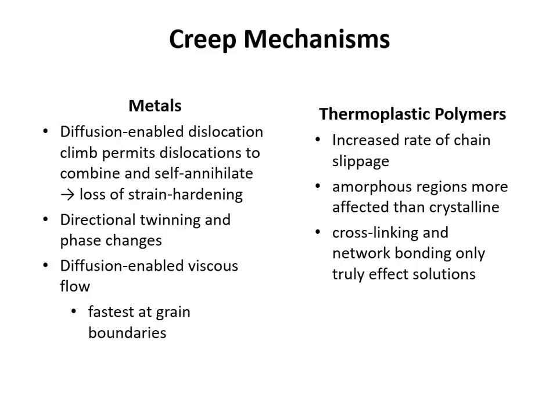You're giving things temperature, so basically the applied stress that a metal is under in service will apply a drive for the material to deform. Generally, this will occur by dislocation movement. You're now giving it enough temperature that things that stop dislocations moving aren't stopping them anymore.